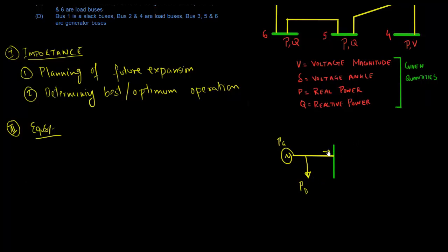Now the power going into this bus is, let's say, the scheduled power, and let's call this bus I. If bus I is then connected to n number of other buses, the total power it's supplying or taking in from these n buses is, let's say, P of I. Now, what we should have is P of I minus P scheduled on bus I. So that's PGI, PDI, and P schedule I.